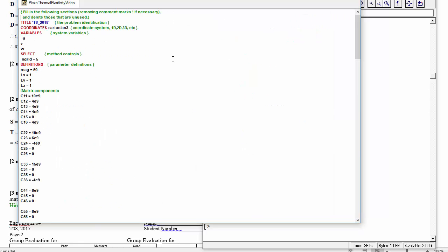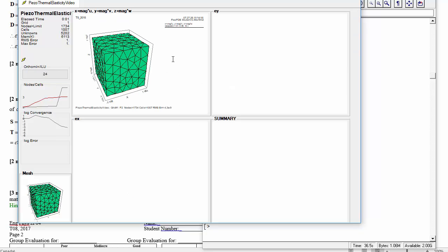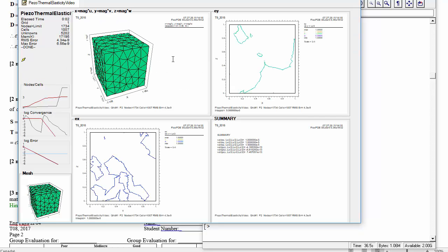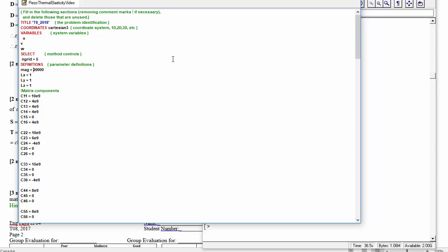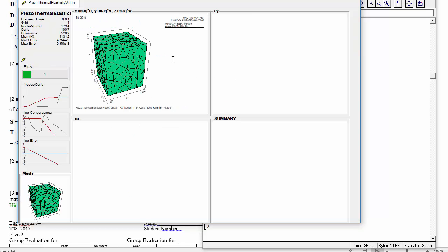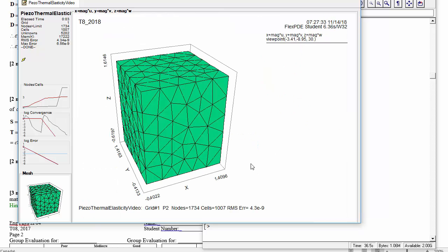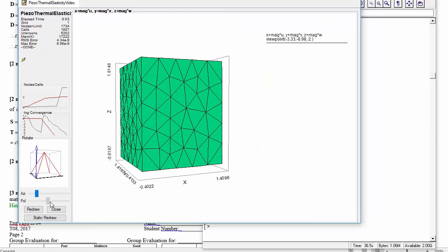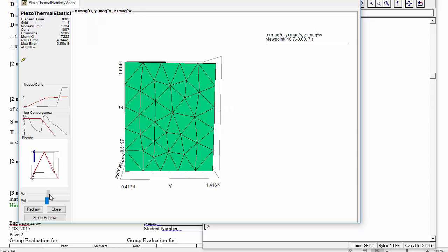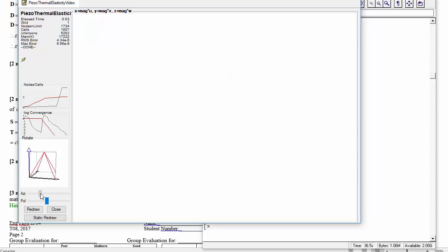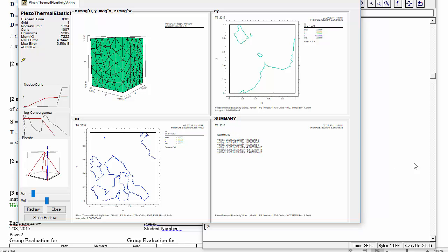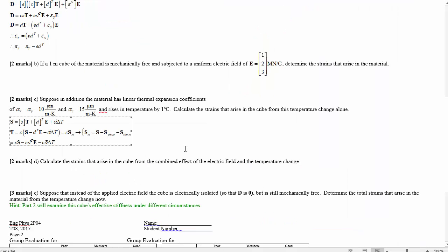Maybe it's time to modify the magnification that we've got on this. We're in the tens of microns, so we probably want to magnify by about 20,000. It's all linear, so it's hard to tell exactly what's going on. 80,000? Yeah, you can see some real cube deformation here. It doesn't look much like a cube anymore. It's all strained out. Okay, so there we go.